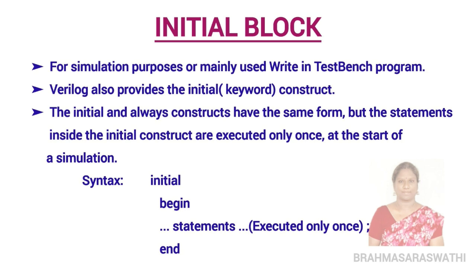The third point is the initial and always constructs have the same form, but the statements inside the initial construct are executed only once at the start of the simulation. This means the initial and always blocks have the same syntax format.